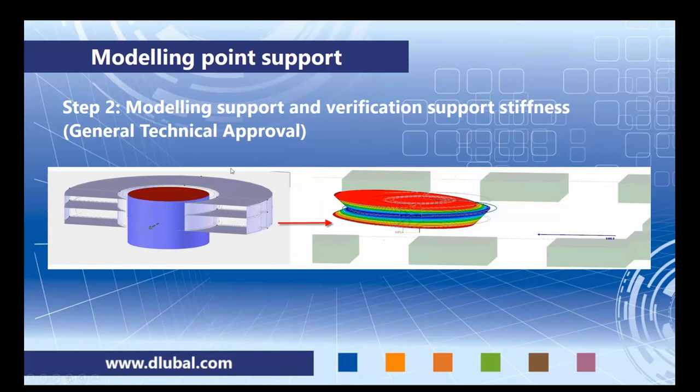So the point support is consisting of this bolt in the middle, two rigid surfaces on the top and on the bottom, and the glass pane in the middle, and two contact solids between these surfaces, transferring pressure and failing under tension. From defined loading and a deformation, a spring constant can be calculated.